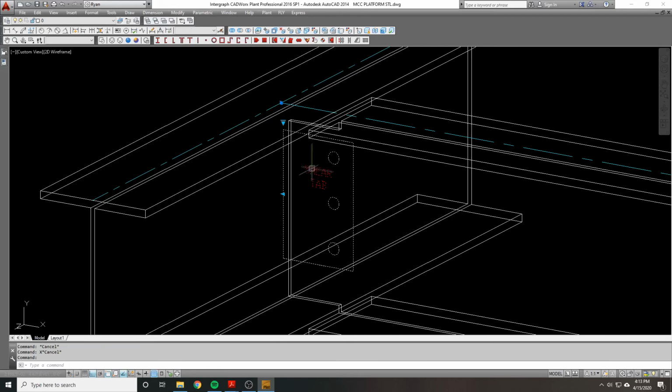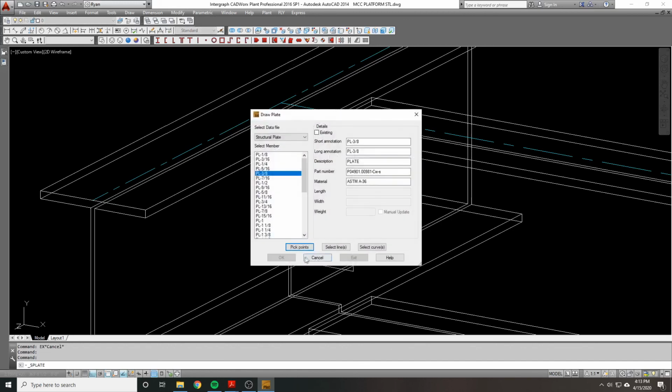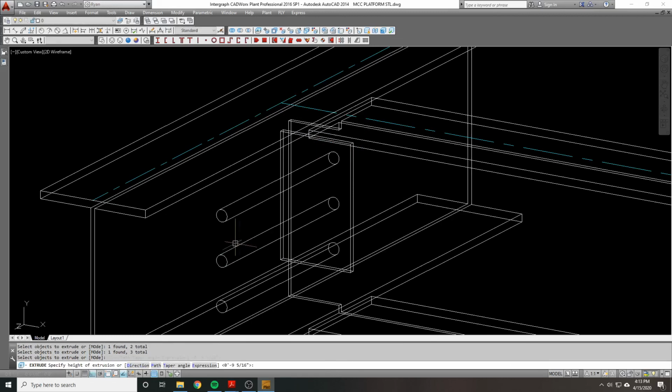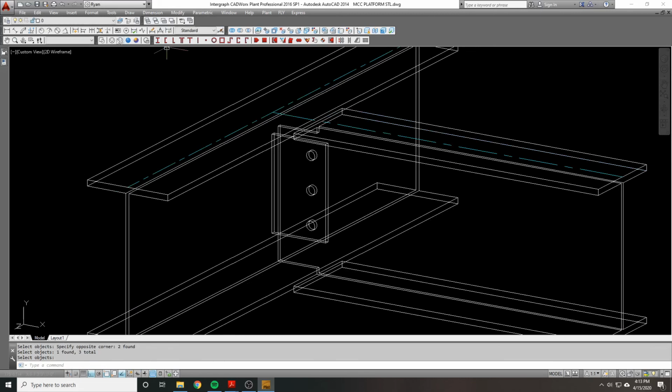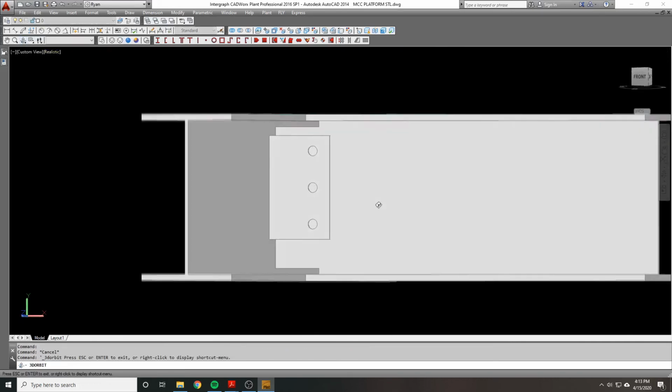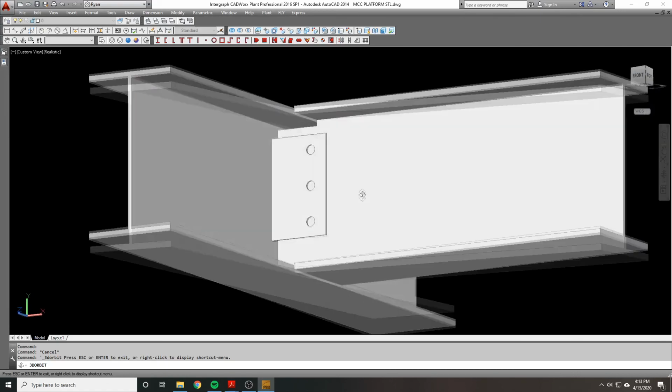That's what's kind of nice about it, is I set this up so that it's going to use pretty much standard default dimensions. I can just leave this alone as is, explode, erase, and then I can use this as a basis for a plate. 3/8 shear tab. I'll have my default dimension from these holes to the center line of the beam at 4 inches, which is pretty common for most of the connections that I do. Oops, I did not subtract that properly. And there we go. There's my shear tab. Quick, easy, painless, done. Quickly throw a shear tab in there.